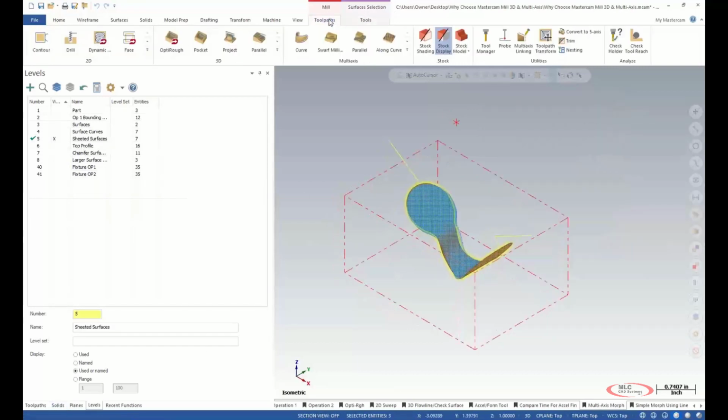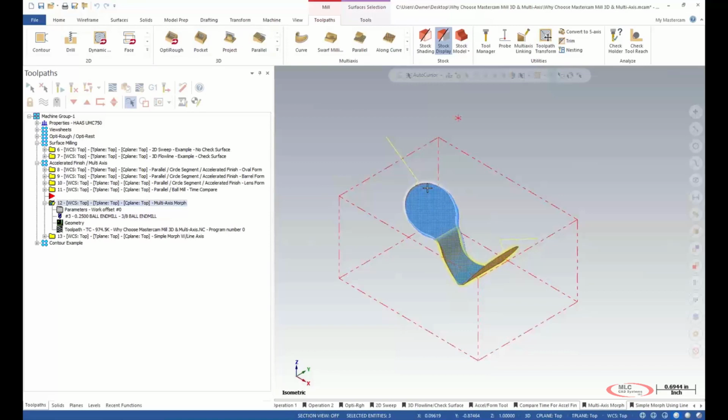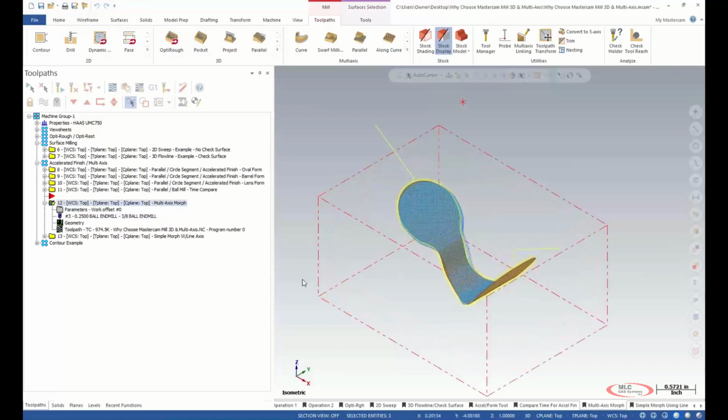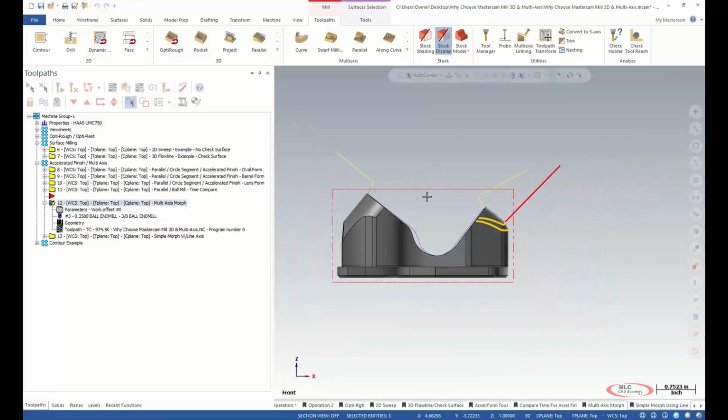When it comes to Mastercam multi-axis toolpaths, what I tell people most of the time is what you get right off of the actual settings, as far as once you select your geometry, if you regenerate it, most of the time you'll have something pretty close to exactly what you want. Then it's just some fine tweaking on how you want to tilt your tools around. What I want to show you next is how we can utilize our morph toolpath again under a 4-axis operation.